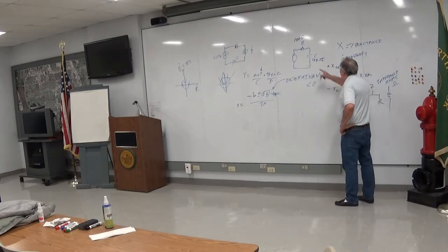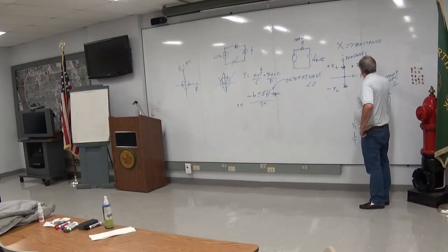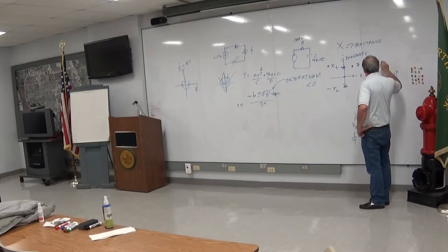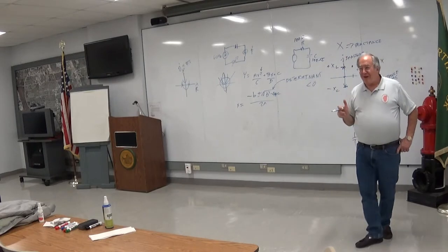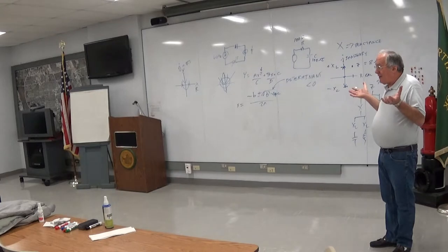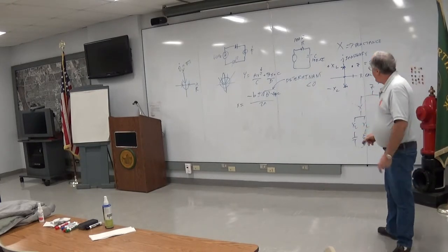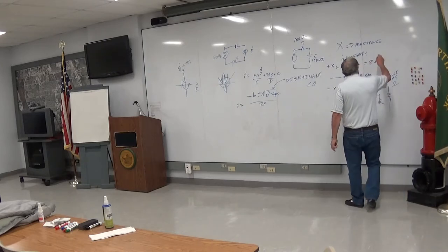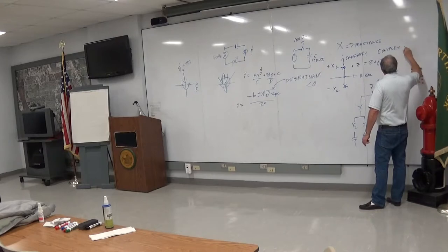And what we have, if we have this and this, is a little bit of this, a little bit of that, and there's your impedance right there. Your value Z is some value of R, and I'm putting J in there just to say there's the imaginary part, some value of X. There'll be a number for R, there'll be a number for X. And that's your impedance. It's got two parts. It's got a real part, it's got an imaginary part. These things have a name in mathematics. They are called complex variables.